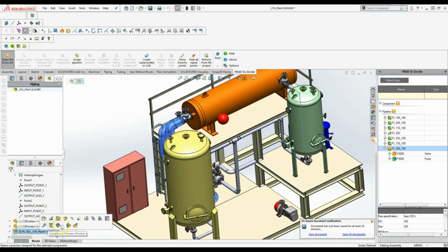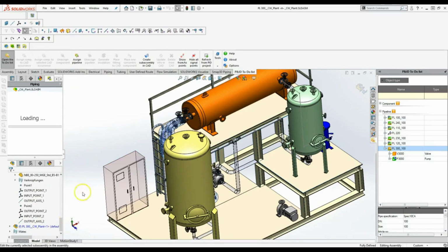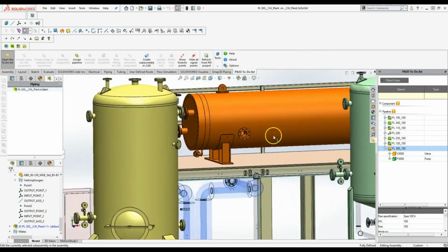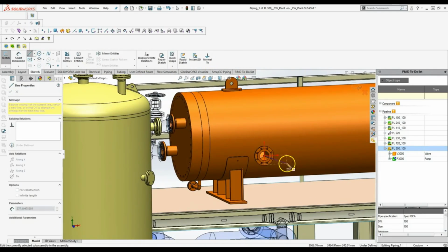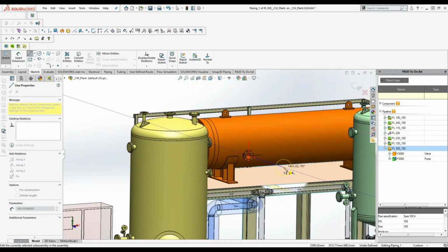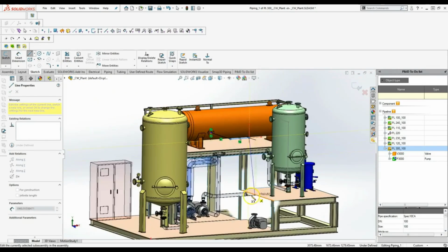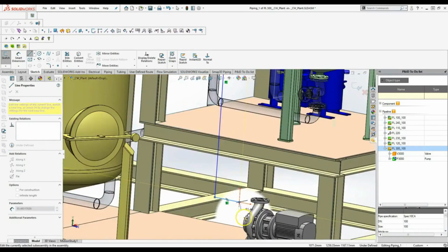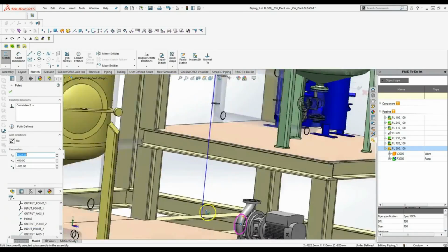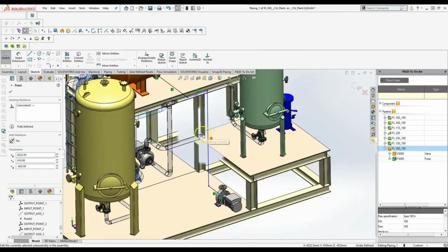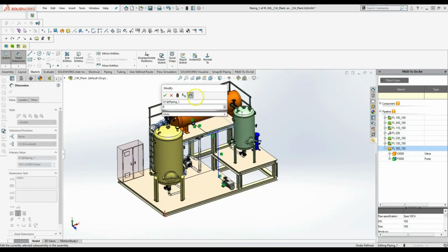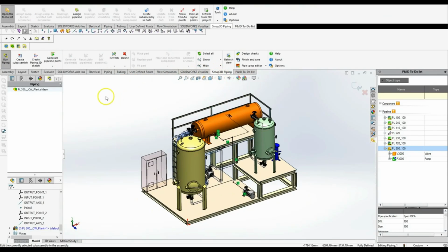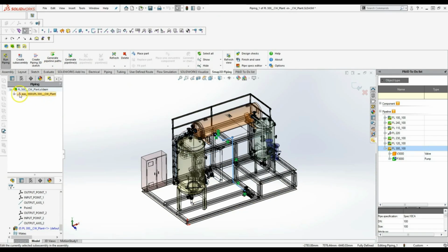To create this pipeline, we need to edit this newly created subassembly from our design tree. From our piping toolbar, we can create a new piping 3D sketch. So we are going to create the route, and the only dimension we are going to place in is the 780 millimeters. So we select Generate Pipeline Path from our Piping tab.